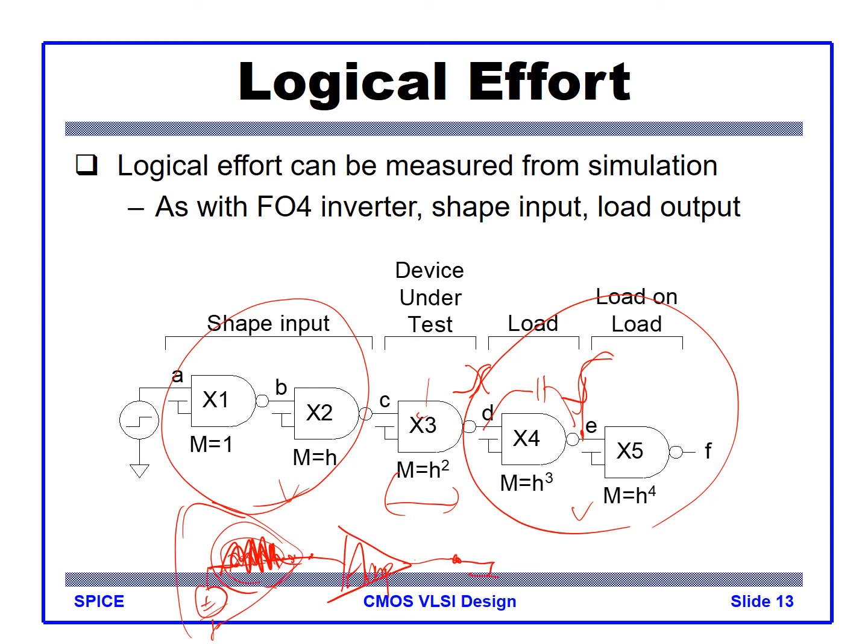You also have to put some capacitance there, because the driving inverter will have an input parasitic capacitance, or a load capacitance. You have to properly model the input and output network. So in both analog and digital circuit design methodology, you have to be very careful about modeling the input and output load, otherwise you will not get an accurate simulation result.